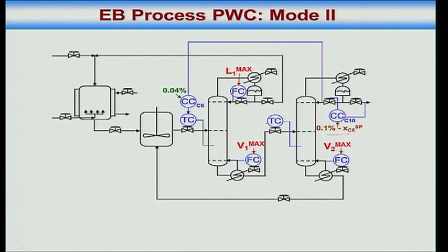It's a stabilization issue. What do I mean by stabilization issue? If I don't control this temperature, I can have a situation where things will drop down and just keep accumulating. If I am making more ethyl benzene in the reactors, then I can boil off in the second column. Where will that ethyl benzene go? It will drop down and keep circulating around in that loop. Yes or no? I don't want that. That's a stabilization issue. That's like a level building up and up and up. It's not a level, but so I put a temperature controller there. That's a stabilization loop. Okay.